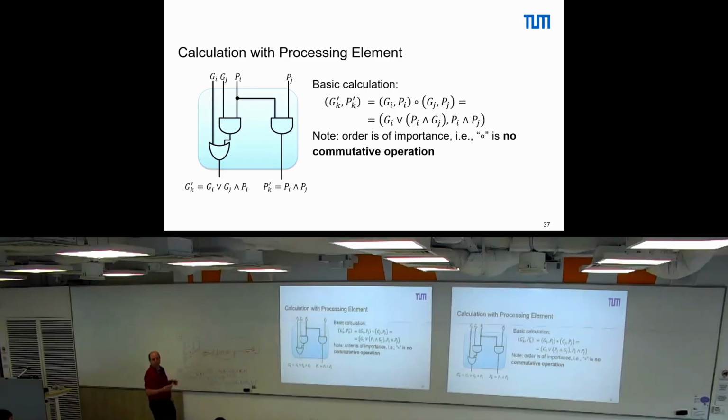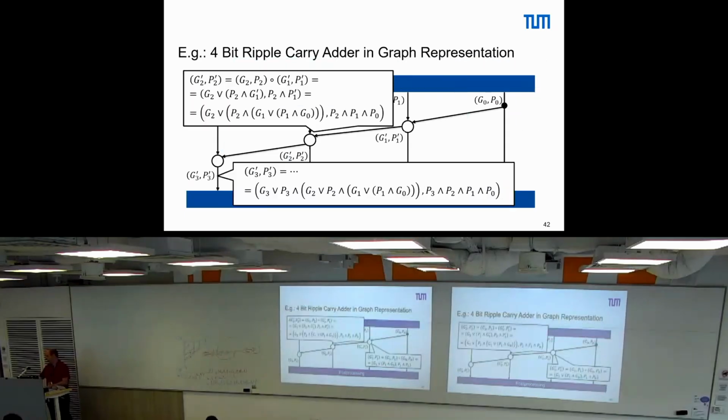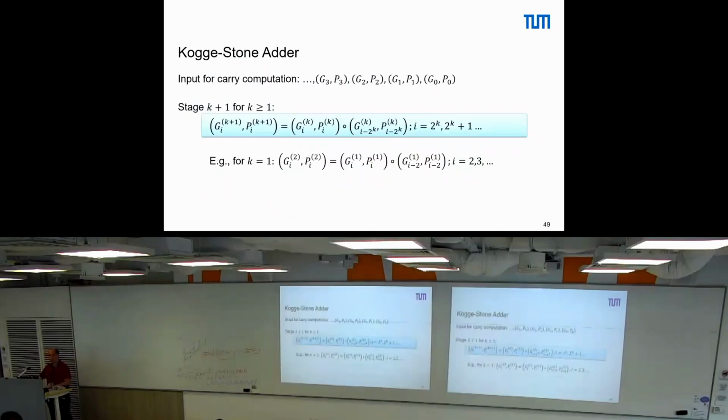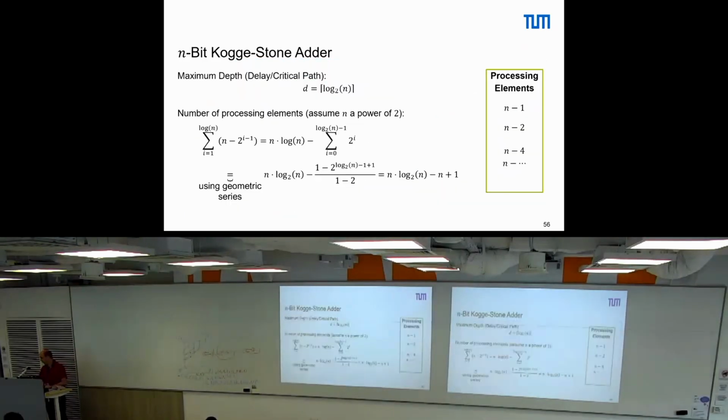computed the correct output. You need to be able to transform always back to this sequence from 0 to n or the other way around. Okay, and then we looked into two examples here. The first was the Kogge-Stone adder, which has some specific properties. If we now compare this Kogge-Stone adder with the second one we have, the Han-Carlson, what does this Han-Carlson do differently? How does Han-Carlson relate to this Kogge-Stone?